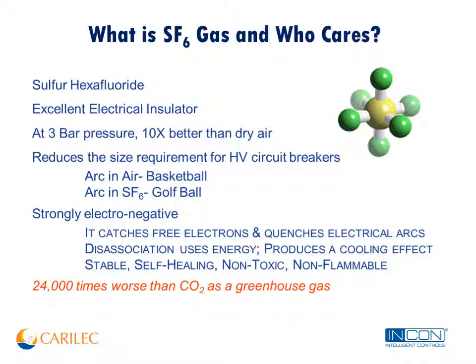So if you're talking about a circuit breaker, an arc that would be the size of, say, a soccer ball or a basketball in dry air will be the size of a golf ball in SF6, and that's why the size of those contacts are sized the way they are. A golf ball will fit inside there, but say the gas went away, you would have it try to operate, but the breaker would likely explode if it had no gas. Could not be made as small.